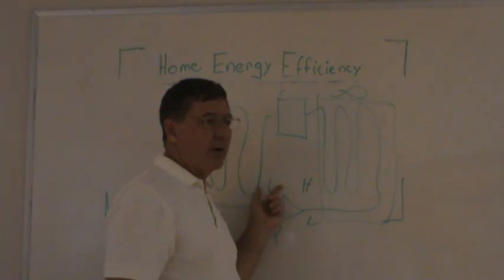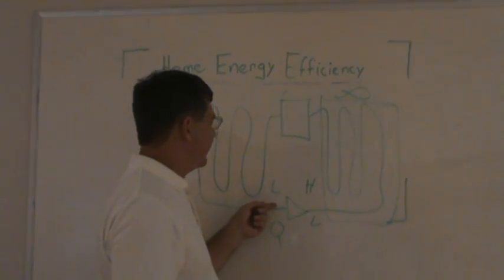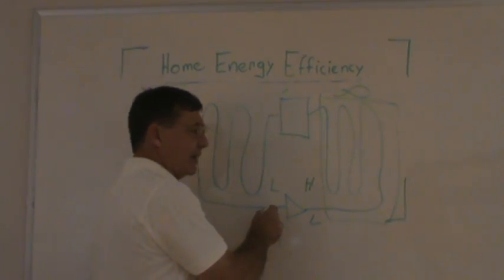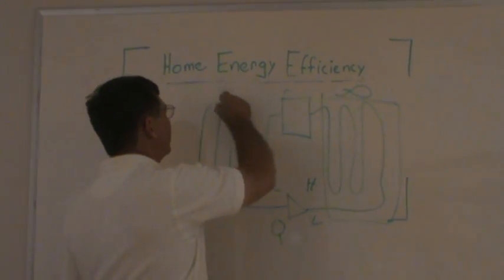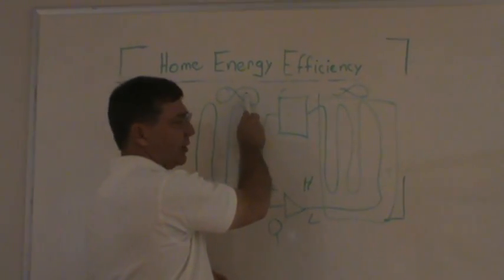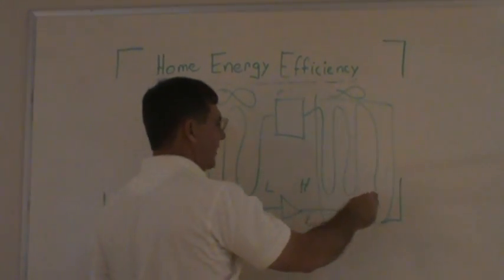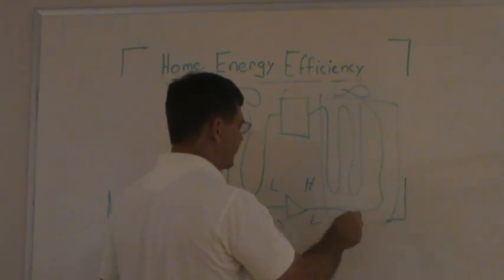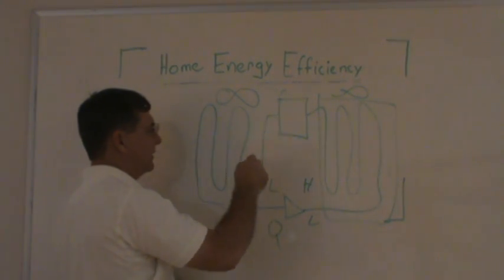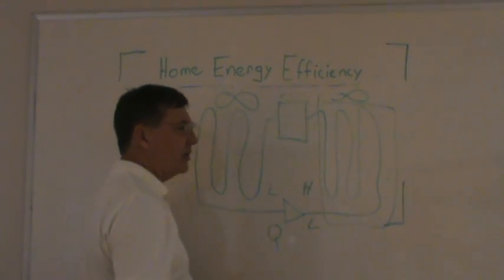And again, that's where our refrigeration takes place, is that when it turns into a gas, it picks up heat from wherever it can, in this case from the copper tubing and also the fins, and then we can put a fan here, blow air across the evaporator coil and into the house, and the cycle completes. It goes from a vapor, drops its heat, turns into a liquid, the pressure changes on it, turns into a gas, picks up heat, back into the compressor. So this cycle goes like this. And this is a mechanical refrigeration.